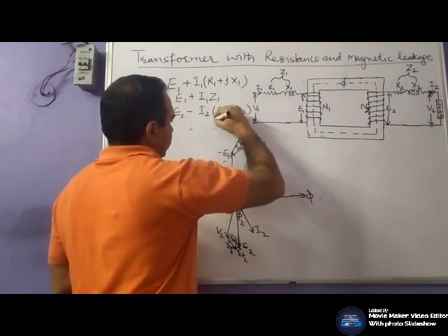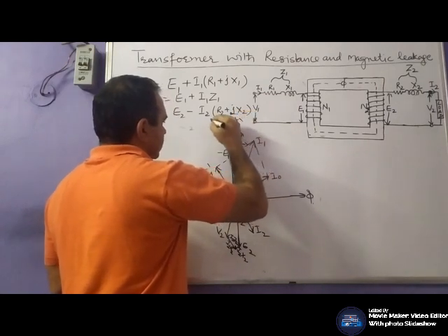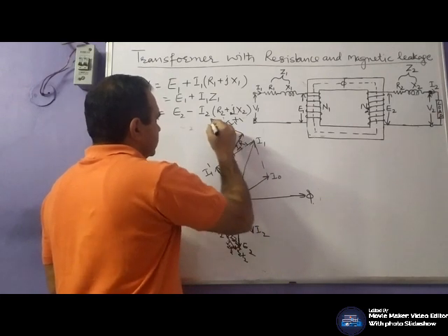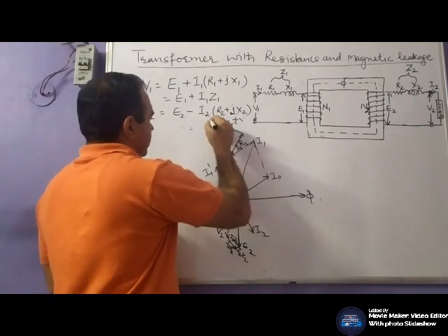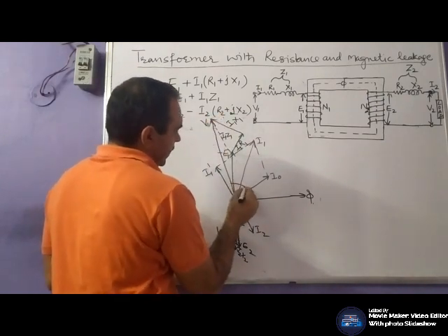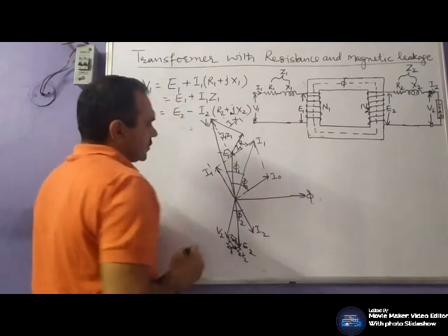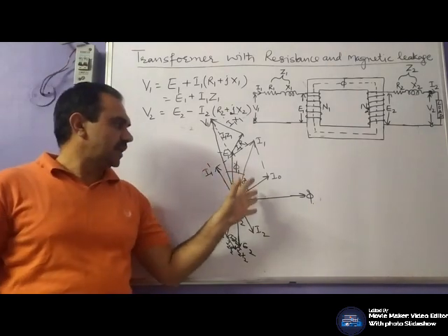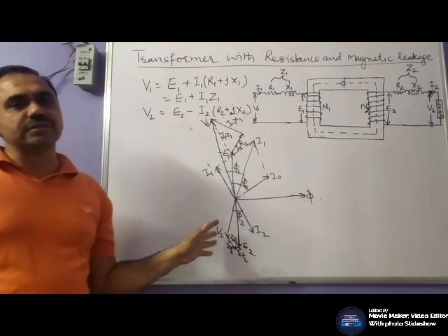It would have a phase angle of 90 degrees. I1 X1, voltage drop across inductor, this will be I1 Z1, and this will be the applied voltage V1. Now indicate your angles phi naught, phi 1. So this will be the actual phasor diagram in loaded condition when the load is of capacitive nature.